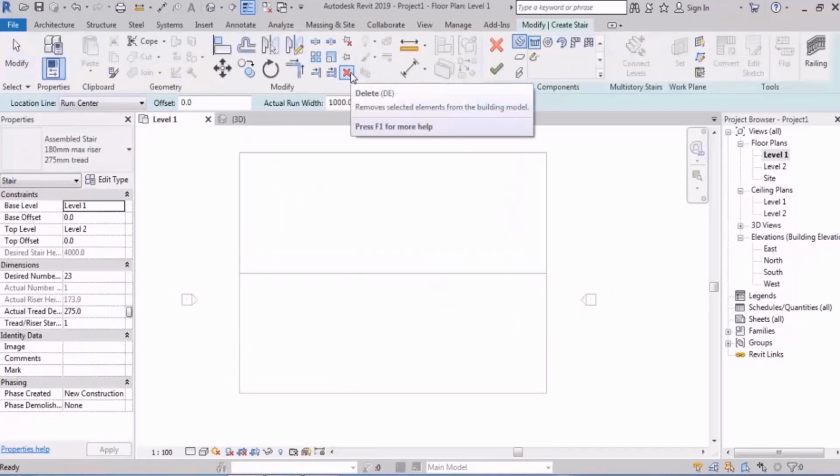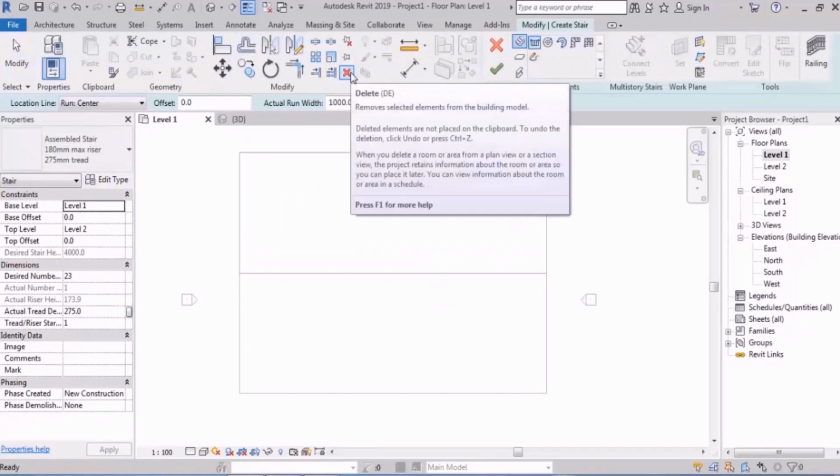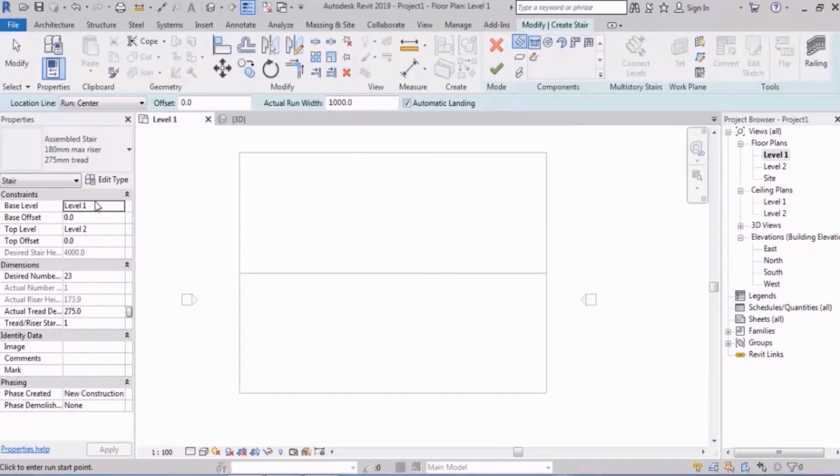Select the stair first. And also remember that any kind of stair that you want to draw, you need to manage the height and the number of risers. So, let's talk about the height first. We say that this stair, for example, is going from level 1 to anywhere. Well, we don't have any level for the 90 centimeter height. And when does this happen? For example, the dock stairs. It has gone up 1 meter, for example, and it's not logical for it to have levels.